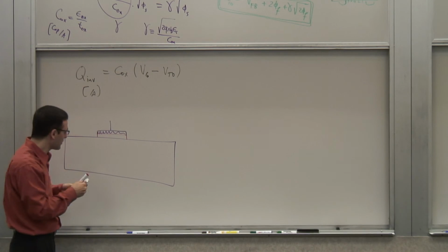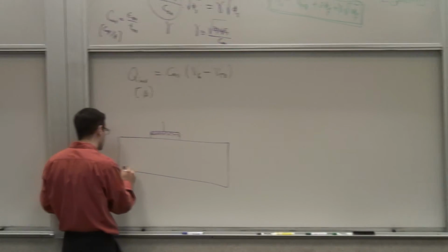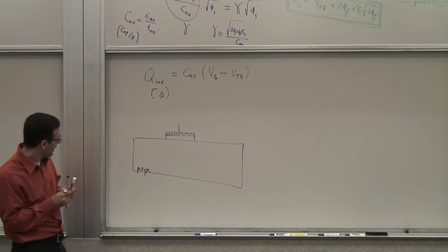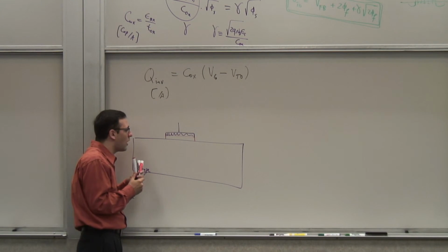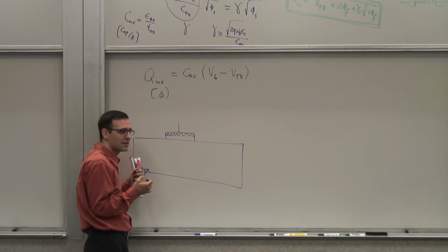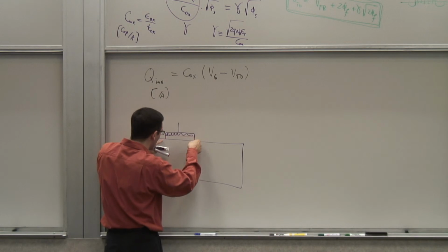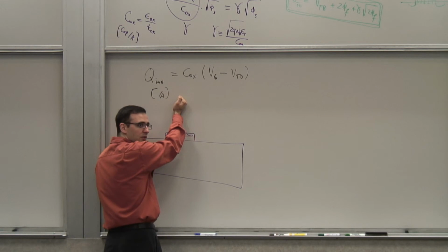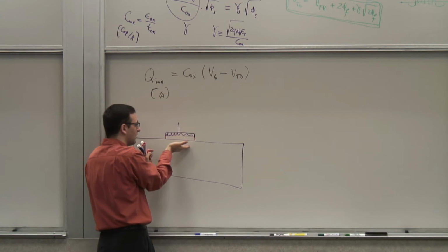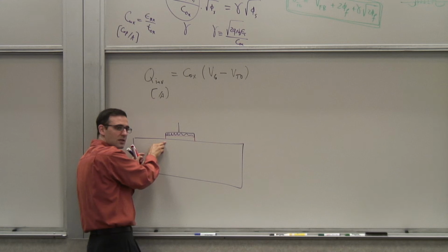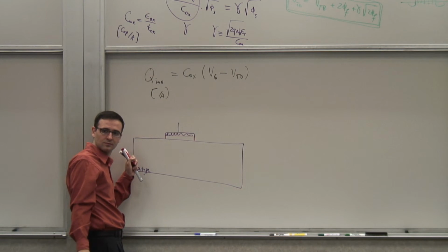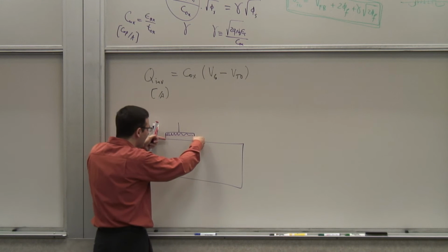Now, in addition to these, I can form a MOS capacitor here, right? And then for this discussion also, let's assume that this is a p-type. I'll change the type, so we've dealt with both types. Now, what I need to do is create two contacts. If I could somehow make a connection to this side and that side, I know, in this case, when I apply a positive voltage here, at some point I invert the surface and I will have electrons here, and these electrons can carry charge for me. So I need to make some contact here.